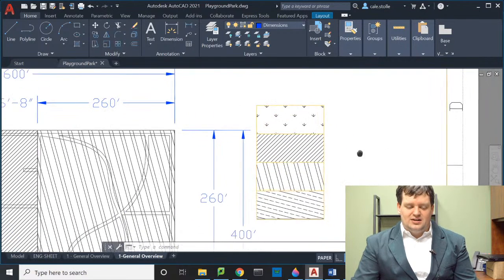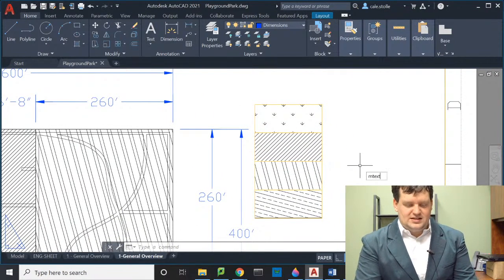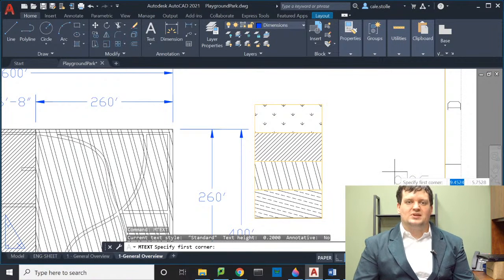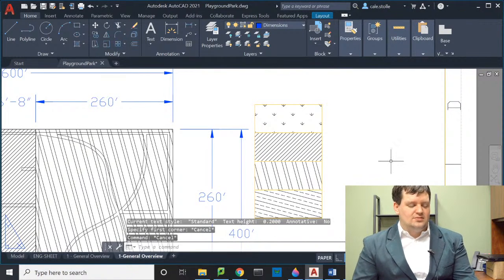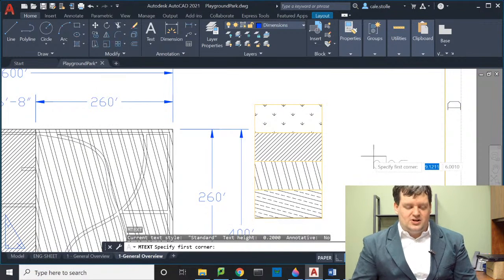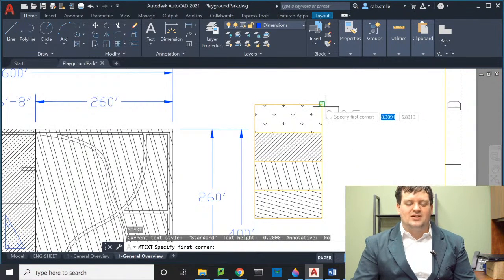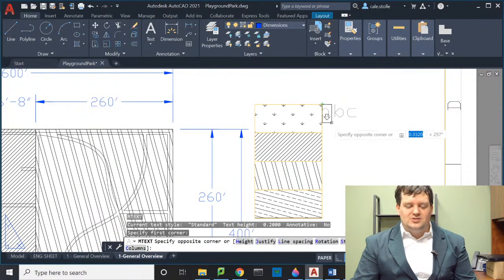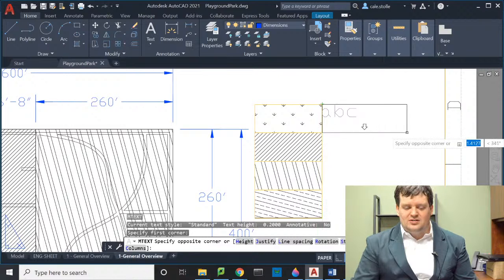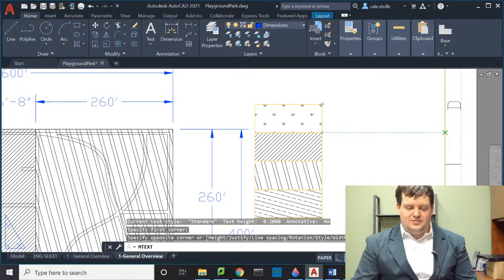Now what I'm going to do here is create a multi-line text box, which I'm used to doing M text because it used to be that T went for a multi-line text box, but now standard in AutoCAD is T does text box, so I should get used to using T. I'm going to go ahead and do it at this corner. I'm going to have it extend from here over, oh, come on. I need an extension line. Come on, there we go. Extension line to there. Okay.